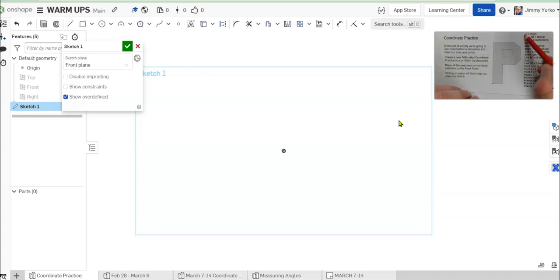So, for example, step 1 here says A origin. Well, our origin is right here on the paper. That's a big fat dot. So we're going to call that A. Line AB starts at the origin, goes 4 horizontal to the right. So A, B, that makes this point B. This is going to be line AB, and that's going to be 4 units horizontal to the right.